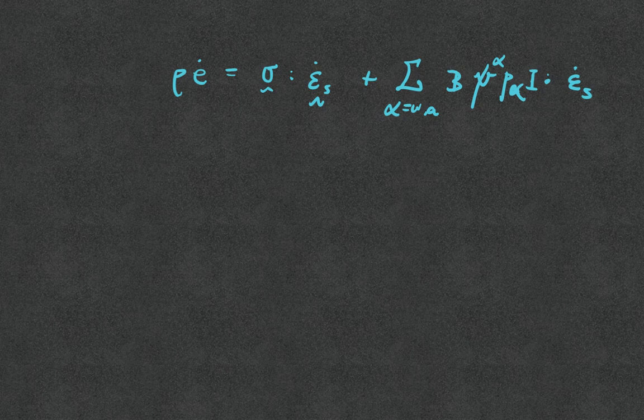Okay, and we don't have degree of saturation because in the fully saturated case the degree of saturation is equal to 1. And in the previous case B also equals 1, but now all these assumptions are generalized. So the solid part is compressible, and hence B is not necessarily equal to 1.